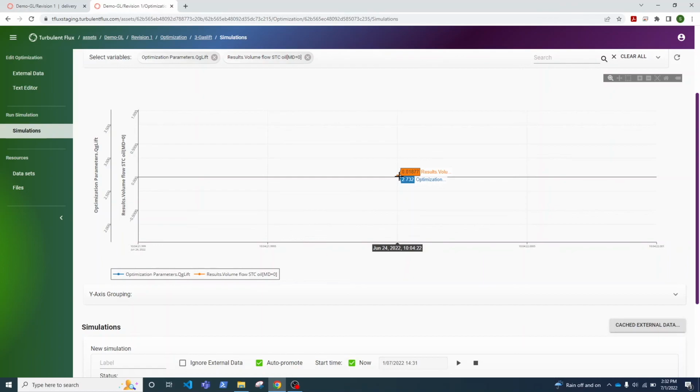If we compare it with the scenario, we said it was between 2.5 and 3.3, then we nailed it down further with the parametric, which said 2.75, and now the optimization has found a single value and is telling us that at gas lift rate 2.732 you have the maximum oil rate.